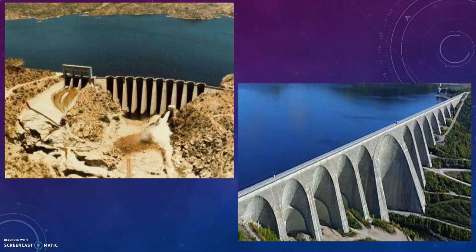The amount of concrete used in buttress dam is about half to one third of the concrete used in gravity dam of the same height. However, the cost of construction of a buttress dam is not low in that ratio because of the increased cost of reinforcement and of form work.